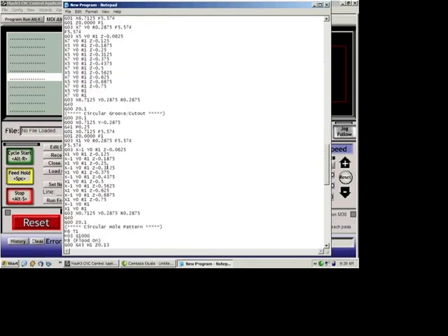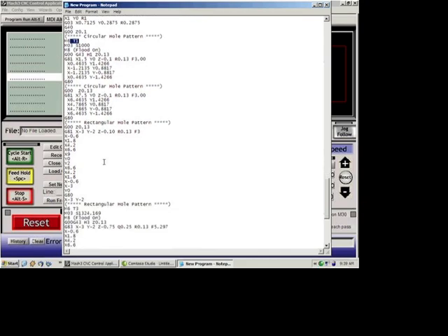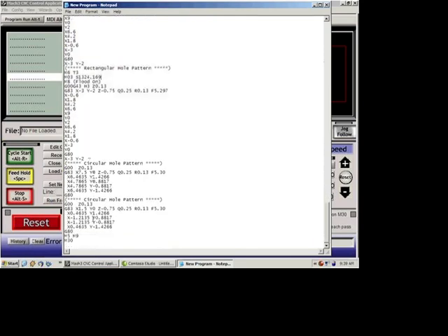We keep going down, and we get into our patterns, and we change to a drill bit. And this drill bit, actually, we set it back to tool 1. This was for our spot drill. Then we get down here, we change it again for tool 3 for drilling with our 375 drill, and then we get to the bottom where it stopped our program.